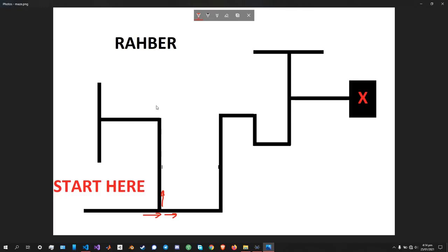So the status here is whether a sensor is on the line or not. Right. So let's say our sensor has reached this point. The robot is here, and we have all these sensors here. Let's choose this sensor here, the leftmost one. So the status of this one is 0. By 0 I mean it is not on the line. So when our sensor is above the line, we will say that its status is 1 or high, and when it is not above the line, we'll say that the status is 0.